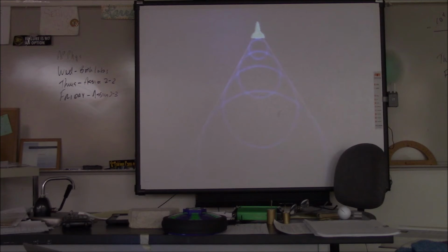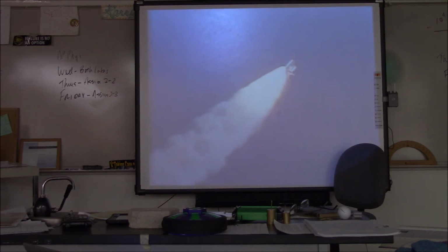The resulting pattern of waves leads to constructive interference taking place, where successive wave fronts overlap, forming a single very large wave front, which carries a tremendous amount of sound energy along with it. This large wave is called a shock wave, and forms a conical shell of sharply increased pressure with the shuttle at its apex. Throughout the remaining atmospheric portion of its ascent, the shock wave will continue to trail behind the shuttle.